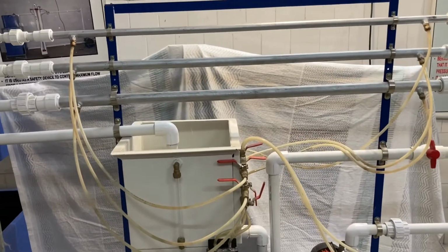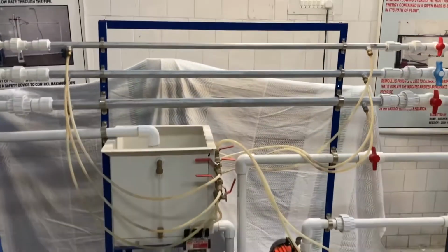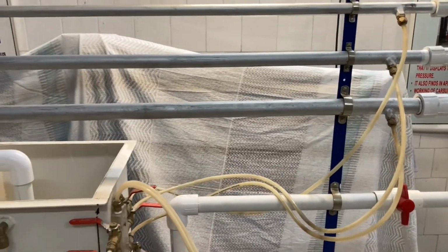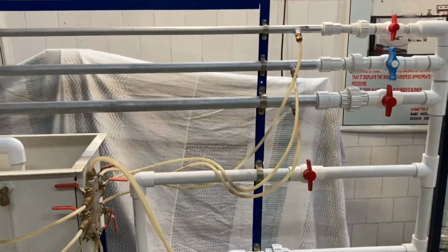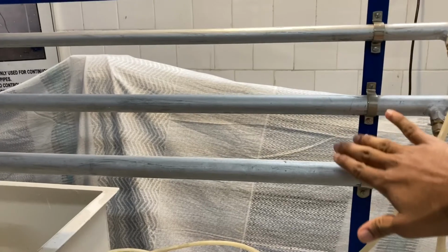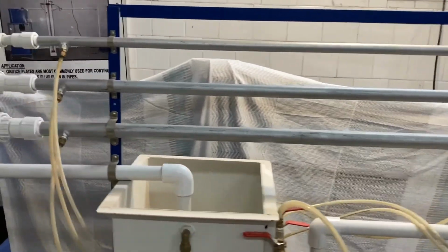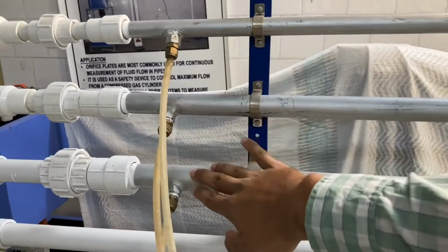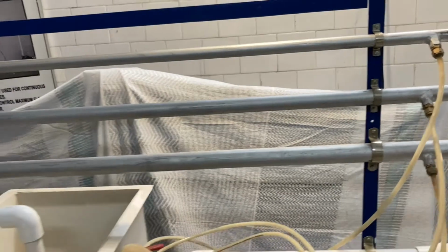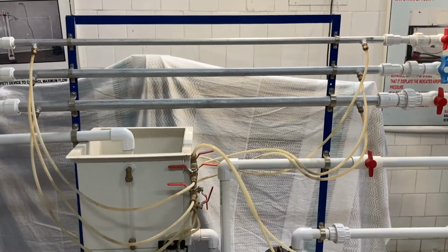Before following the procedure, let's try to know about the apparatus first. So this is the apparatus which we call the fluid friction apparatus, and as we all know, here we need to find out the friction losses and friction factor for these three pipes which are of different diameters, and these are the points where we have connected our manometer, and as you can see, the length between these 2 points is the same for all the three pipes.